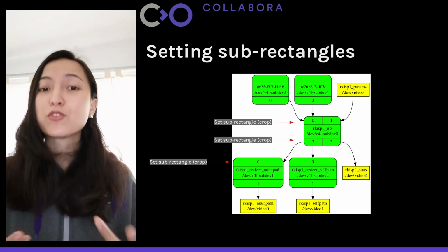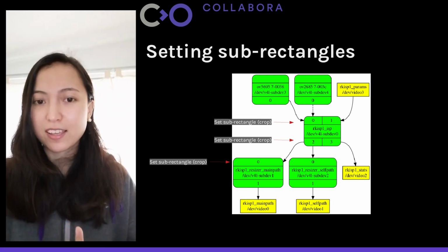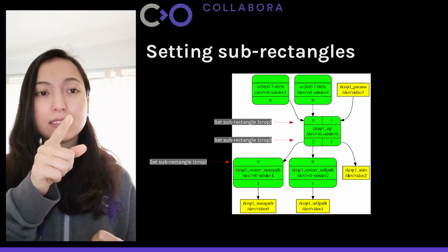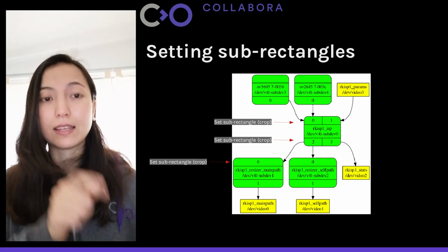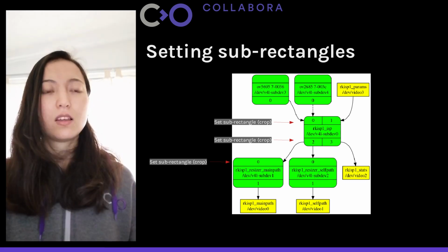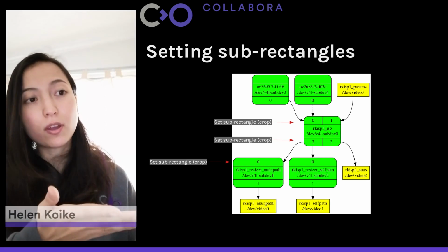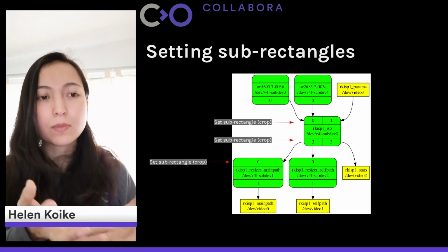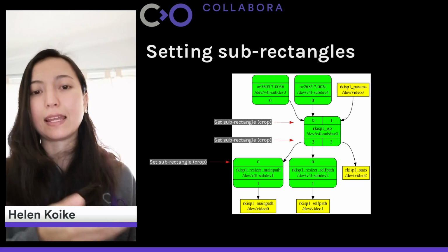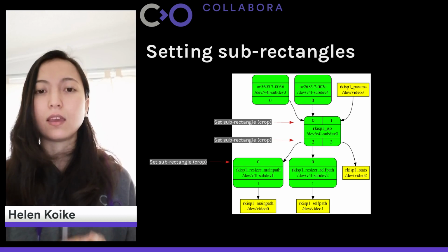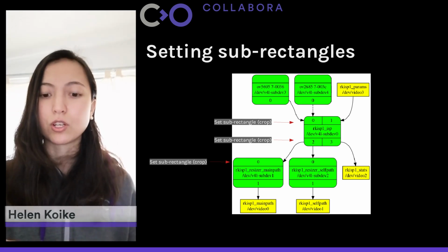That means we need to allow user space to select another subrectangle, and we expose this one in the pad 2 of the ISP. So we have 3 points to select subrectangle, then exposing this just in a single point and allowing auto configuration doesn't make much sense. That's why in this case we have manual configuration propagation.